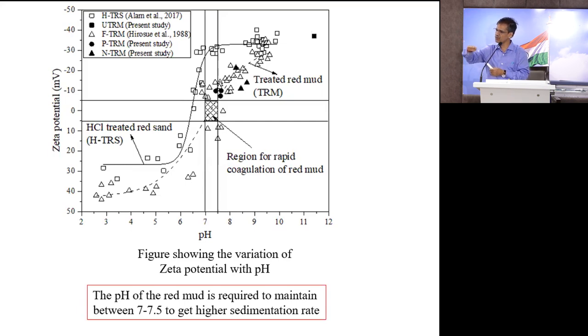I put one layer, then I start dumping, so the top where the roller goes becomes hard, somewhat impermeable. Then as you keep dumping, the seepage water, even 20% or 40% water present in dry stacking, settles on top of it. That is nothing but sodium hydroxide and so on, which gets a white color.